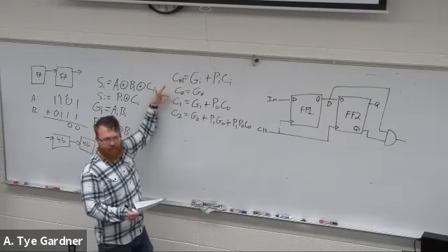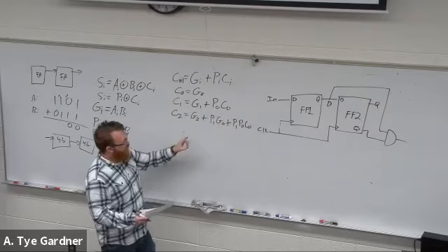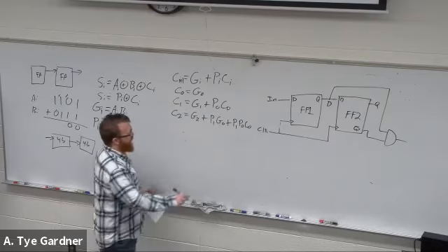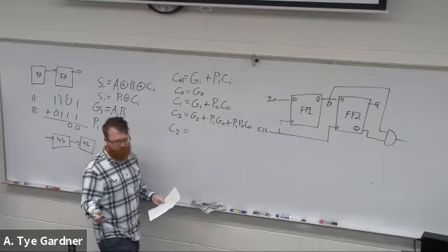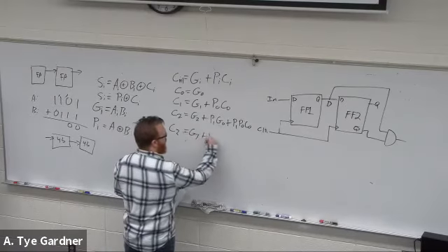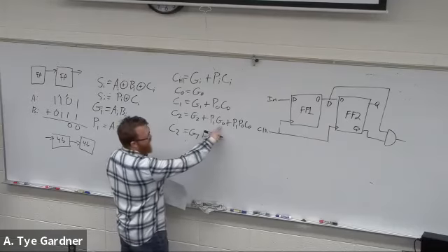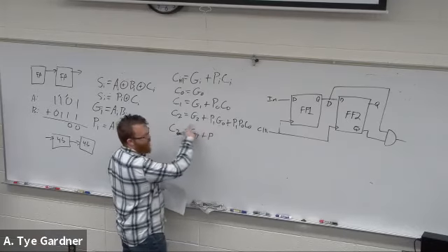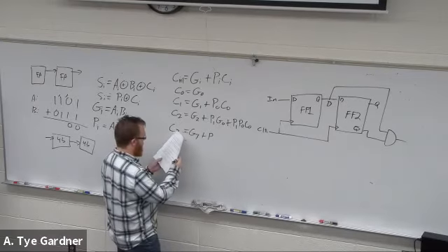There's 2 conditions, right? Either I can have a carry in or I can't. Well, unsurprisingly, C3 gets worse, right? Does it have a carry out if he made his own? Let me make sure I do this right real quick, but basically you can see where it's going. We generated something at 0 and we propagated it down the line, or we generated something at 1 and we propagated it down the line.